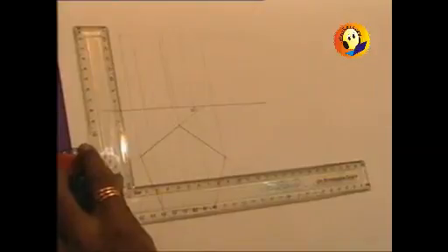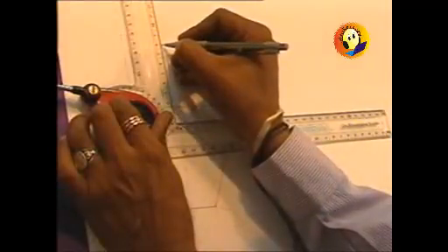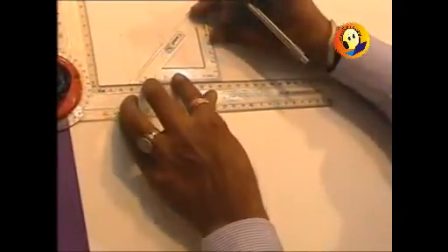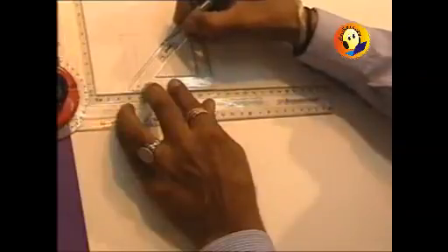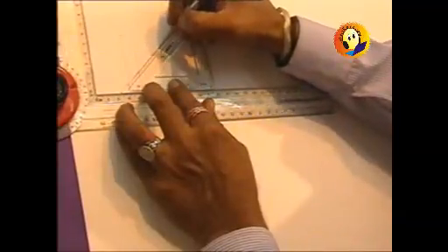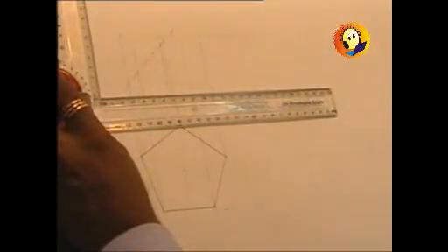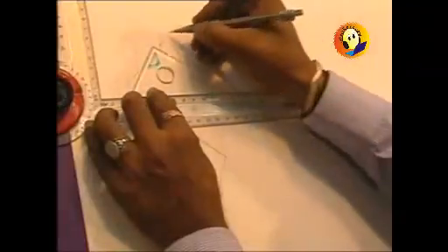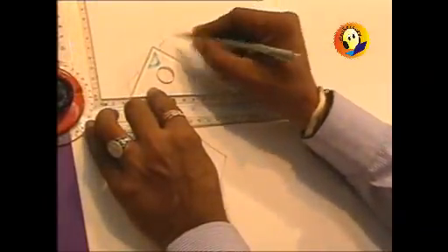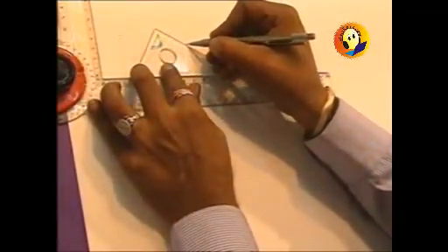The first cutting plane that is given to us is passing through the point on axis, which is 10 mm from the top, and is making 45 degrees. So we can draw that cutting plane. And it is said that the other section plane, which makes 30 degrees, passes through that point of the front view through which the previous cutting plane is passing. And so the second cutting plane can be shown in this manner. So this is how it is cut.